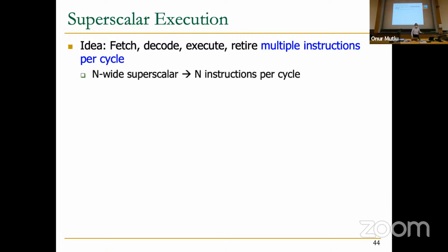So basically, n-wide superscalar means you fetch, decode, execute, and retire n instructions per cycle. But parts of the machine can be wider internally, as we saw in the pictures. Like the Apple Firestorm had, I think, a total of maybe 12 execution units or more, even though it's not fetching 12 instructions per cycle. Because sometimes you have more parallelism unleashed by out-of-order execution internally. More instructions become ready at a given point in time because of the dependence chain in the data flow graph.